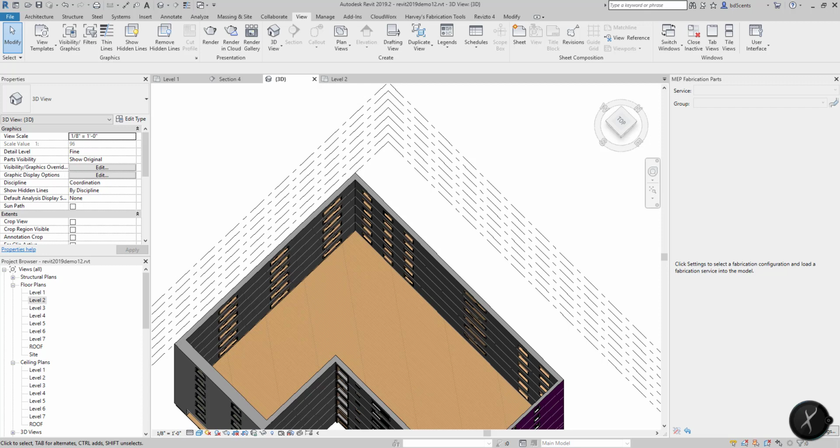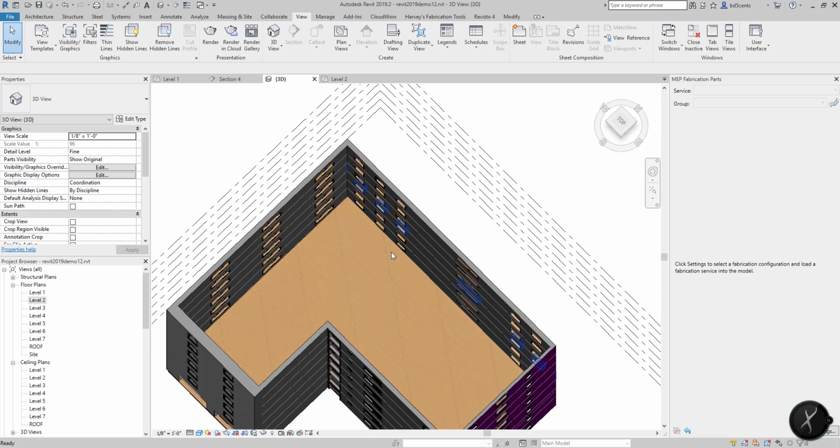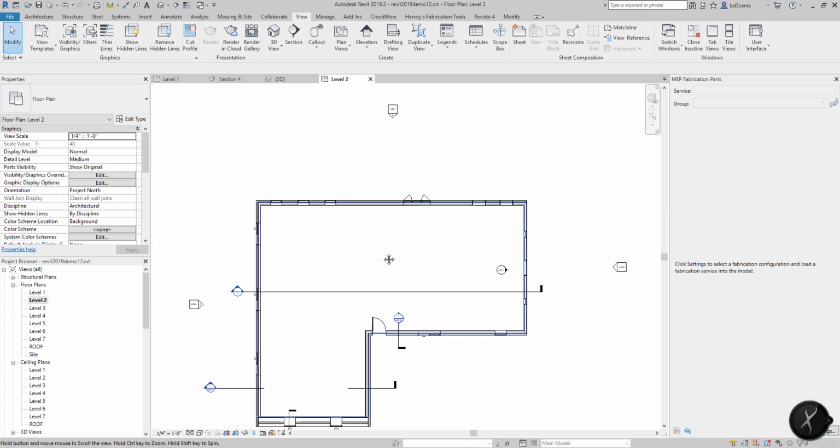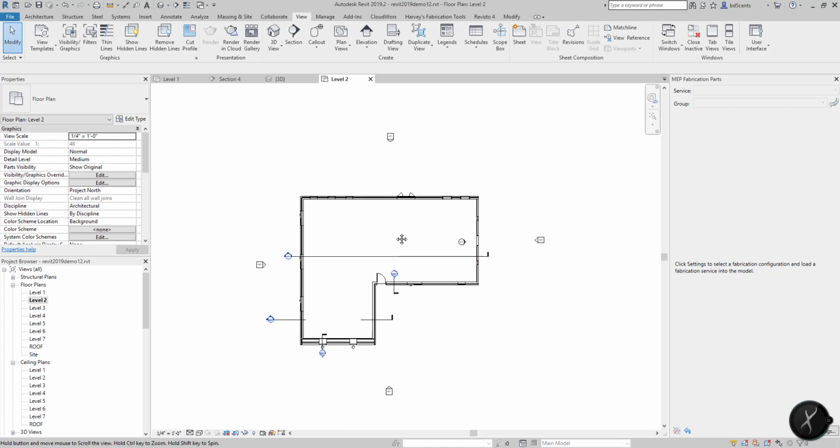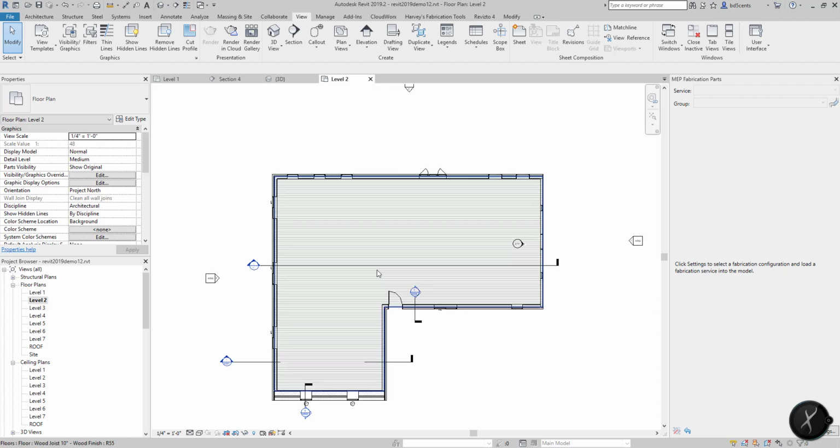And number two, for hints, you will have to make decisions on what to create in 3D and when creating in 3D is just too time consuming and not cost effective. That's the most critical part of Revit, is understanding what to model versus what not to model. Your 2D overlay geometry will not show in other views, i.e. the 3D model. So that's the end of lecture 13.